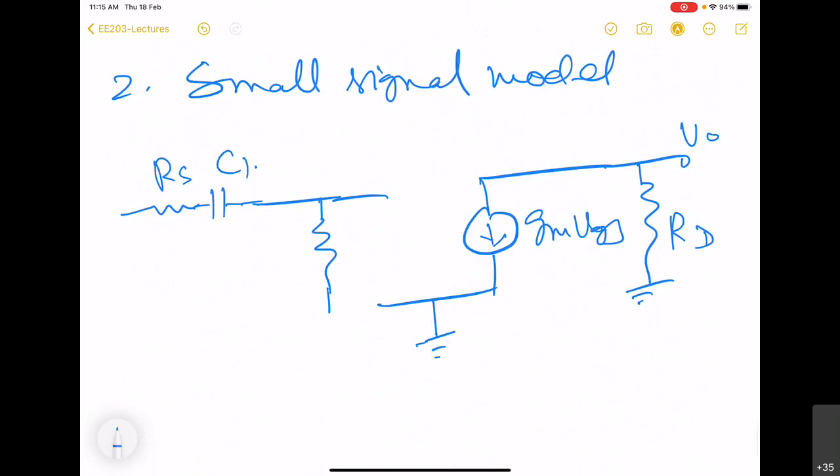So there is one resistor, R1 parallel R2. And then here we have our input, right? So here you can see that source and the other end of the bias resistor are grounded. So we can combine them and represent in this way. Here the important voltage is VGS, which actually becomes the voltage across this parallel R1 and R2 bias resistors.